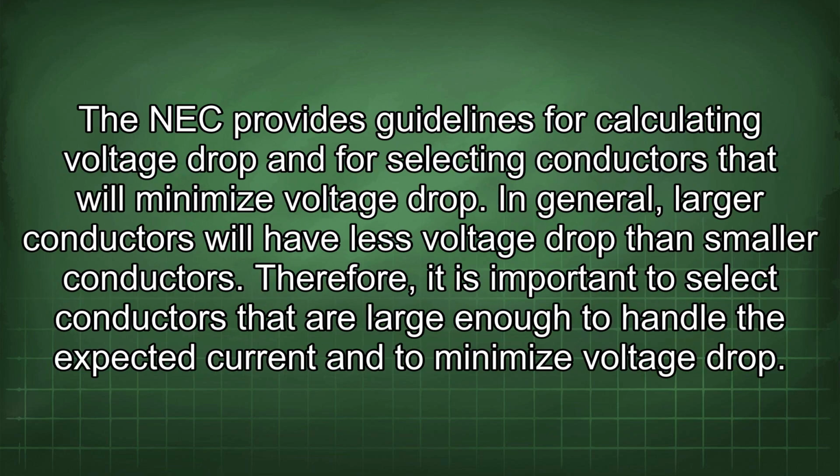The NEC provides guidelines for calculating voltage drop and for selecting conductors that will minimize voltage drop. In general, larger conductors will have less voltage drop than smaller conductors.